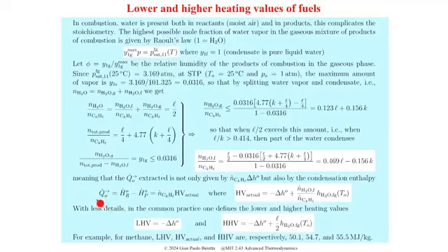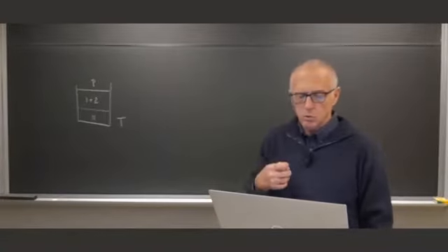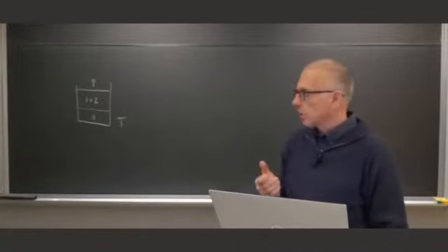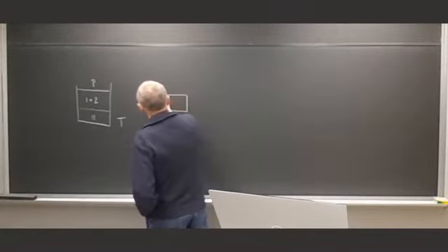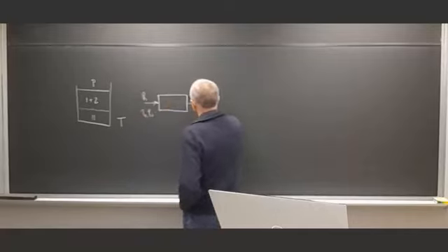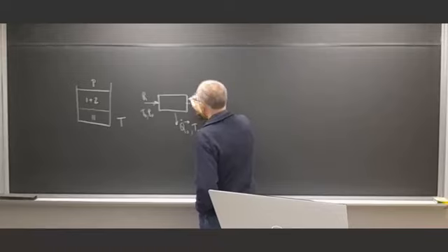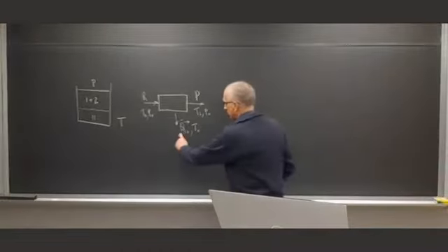And so when you compute the heating value at standard temperature, you're actually making an experiment in which you have your reactants come in at STP, produce your products, and you need to put some heat out at temperature T0, so as to cool the products down again to this temperature here.